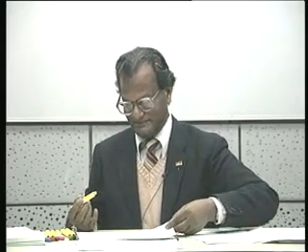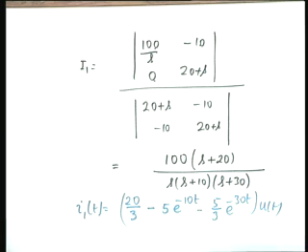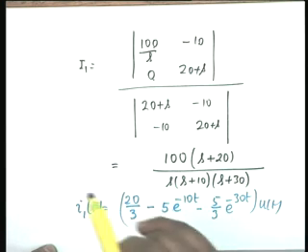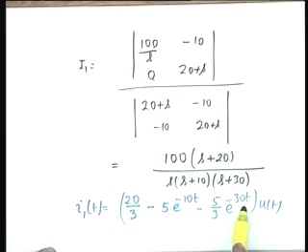For this expression of I1(t) at t equal to 0, we are getting a constant, sir. You are getting a 0. How come this 20 by 3? 5 is 15 by 3 and this is 5 by 3. This is a very interesting point raised by him. You see, I1(0) is 0, inductor current initially de-energized, and therefore at t equal to 0 this must be equal to 0. 20 by 3, this is 5 by 3 and this is 15 by 3. 15 plus 5 is 20 and 20 minus 20 is exactly 0. It has to be. This is a check.